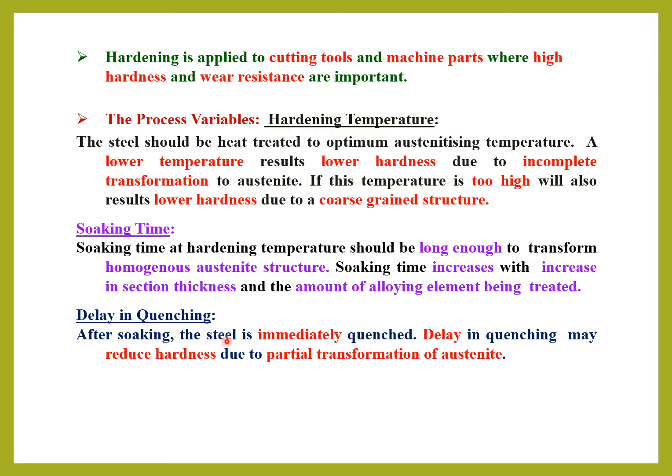We have various quenching mediums, so we can choose the correct quenching medium as per our requirements and then do the quenching process. If we take some delay in quenching, it will reduce the hardness. So this also plays a vital role.